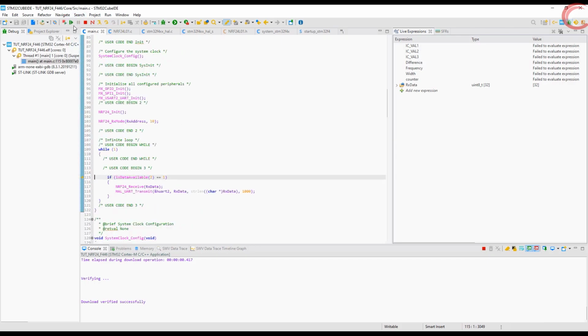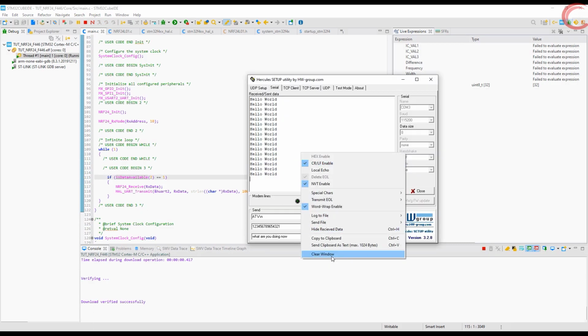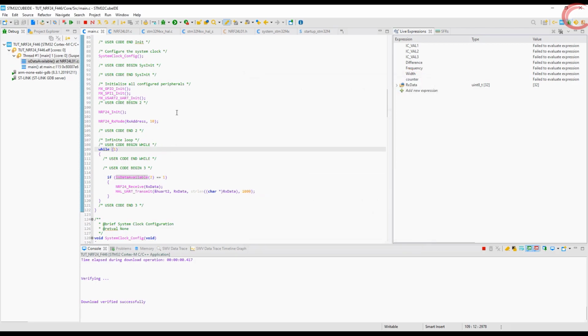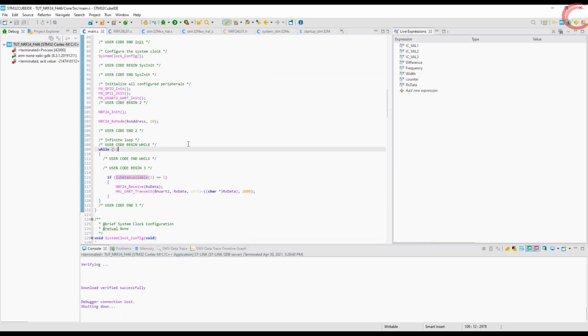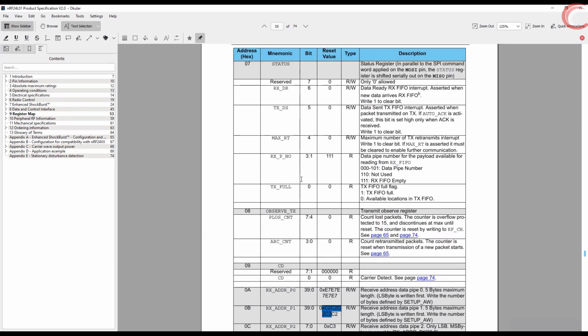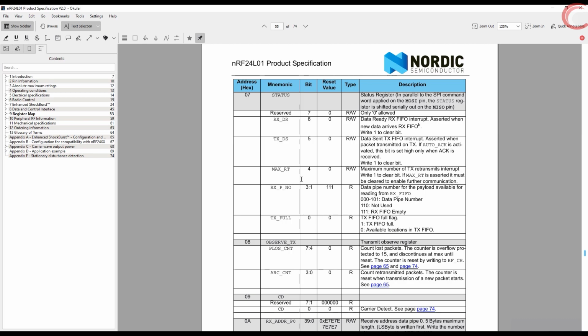If you face any problems, you should test the transmit code separately, like I did in the second video. Once you are sure that the transmit is working, then test the receiver. Also, you can create a function to read all the registers, and print them on the console, just to make sure that the values are set as per your requirement. I will include that in the final code anyway.